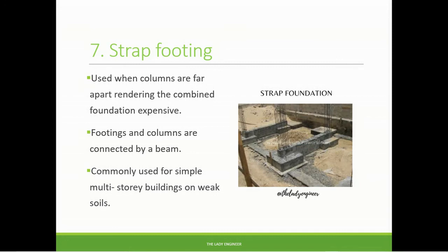Now you can imagine when columns are further apart and covering the entire area with a very thick concrete. That's going to be expensive. So this type of foundation is connected by beams as shown to distribute the load from the building. It is commonly used for simple multi-story buildings on weak soils.